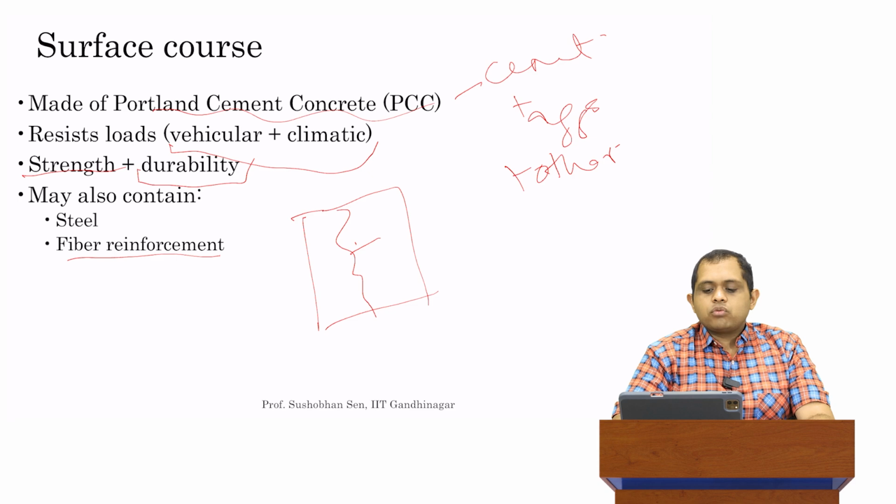The purpose of adding fibers to the concrete in this case is to hold those cracks together. That is, as long as the crack width is very small, and this is something you can also try if you go out on a rigid pavement, you can basically drive very comfortably and very safely over it. The purpose of adding fiber reinforcement is to try to keep the cracks as close as possible so that you can still have a safe and comfortable ride.